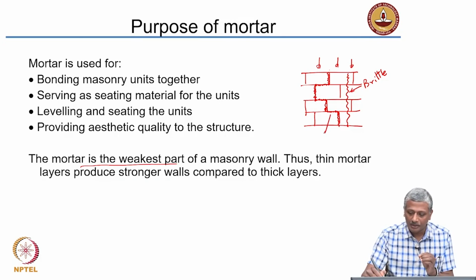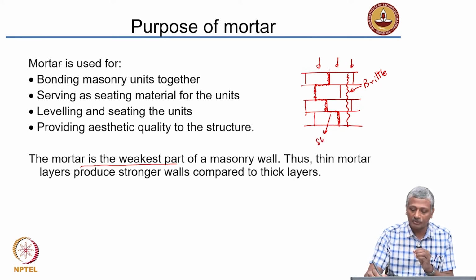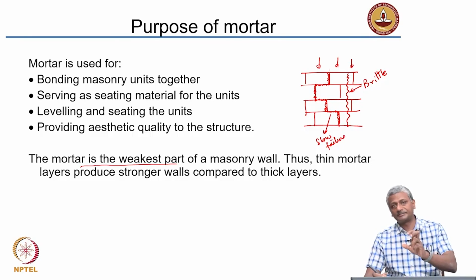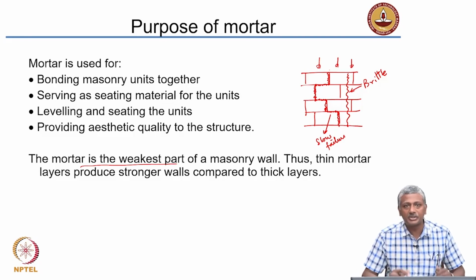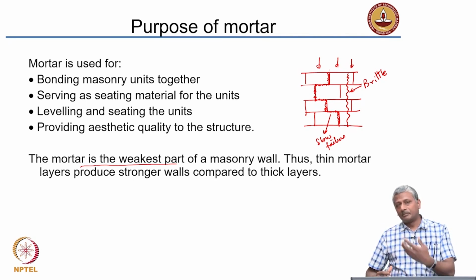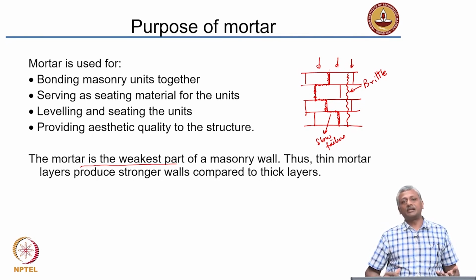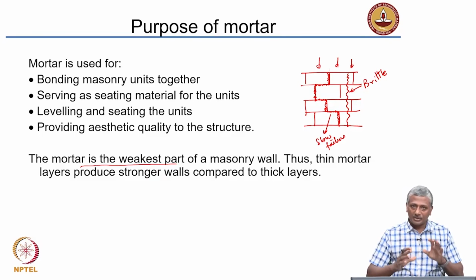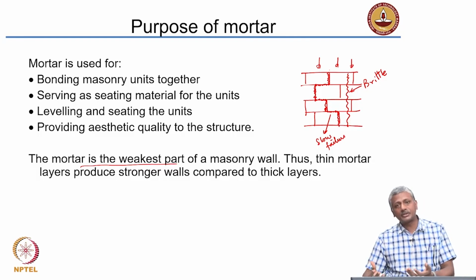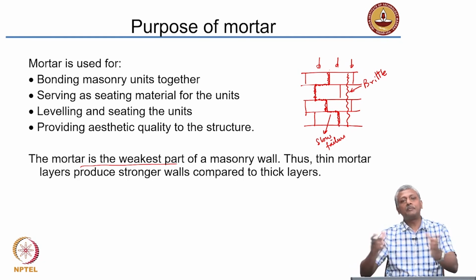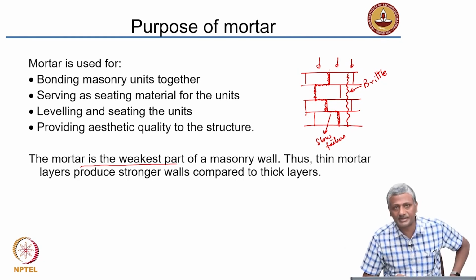So, that is what you get when the mortar is weaker, you get a slow failure. It may not be a ductile failure, but you will get a slow failure. Not like metals. Ductility in metals is a completely different order. So, here we are talking about slow failure, which gives signs of damage so that people can be evacuated from the building. But a brittle failure will be a sudden failure. So, you do not want to create mortars that are stronger. You want to have mortar designed weaker than the masonry unit. The other part is, even if failure does occur, the masonry units are still intact and can be reused. You don't have wastage, for example.